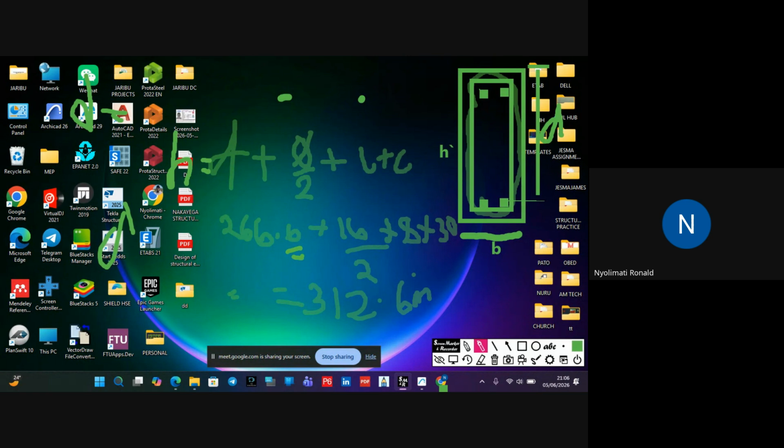Now you can go back for slab. For slab, you take the nearest 25. For example, if you have gotten your H to be 145, the nearest 25 is, like that, interval of 25: 50, 75, 100. Yes, the nearest.